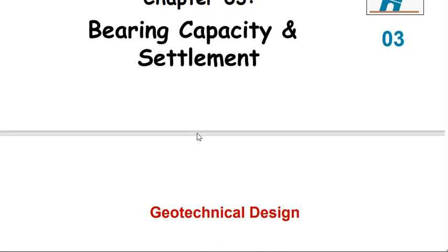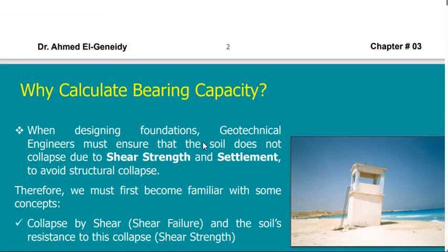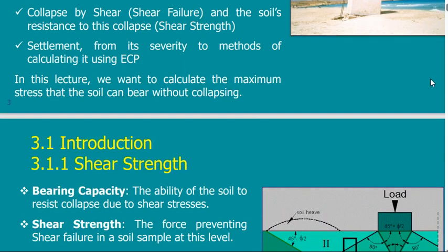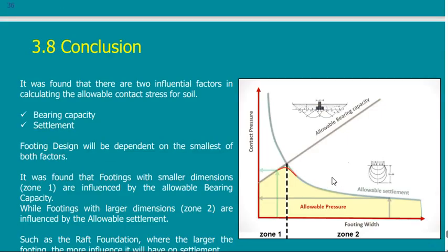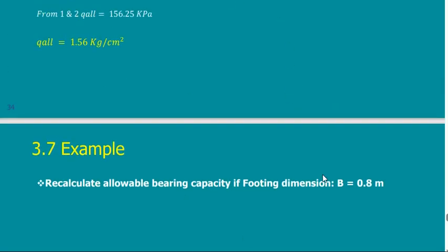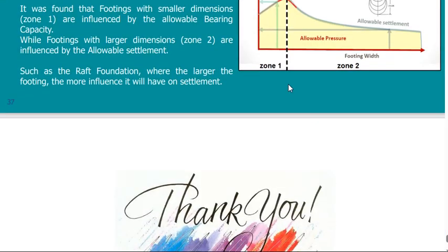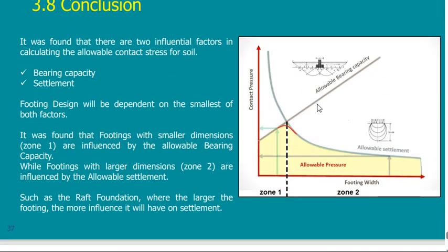We go to the bearing capacity. Of course, we said that what is very important in the bearing capacity is the final figure. This is important. You should understand it and know what it is, because all that we have said before is to reach this understanding. What is this understanding? That in case of changing the width of the footing, I have a different allowable contact pressure, or allowable soil stress, that the soil can take.